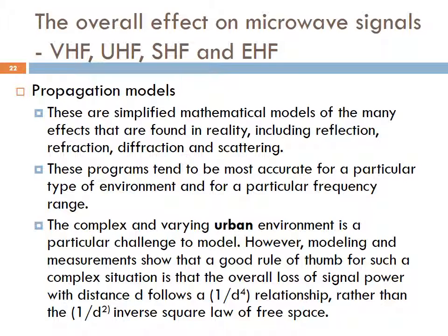In any complex environment like this, received signal power varies for many reasons, including movement of the transmitter or receiver or changes in other elements of the environment, such as passing vehicles, rain, or trees moving in the wind. This variation of signal power in time or in space is termed fading.